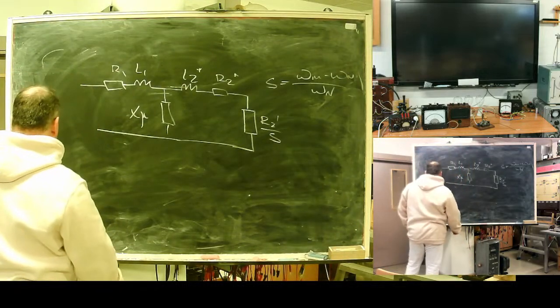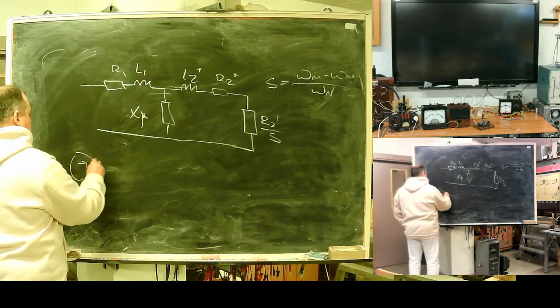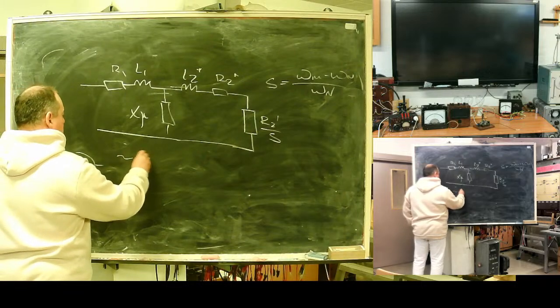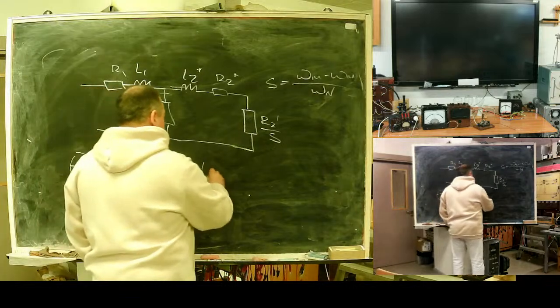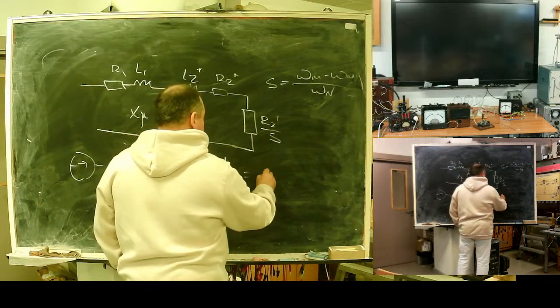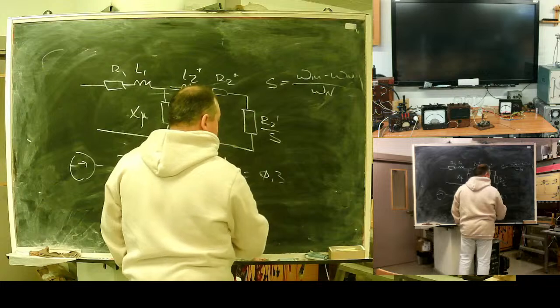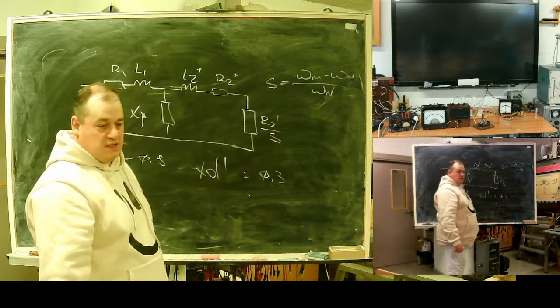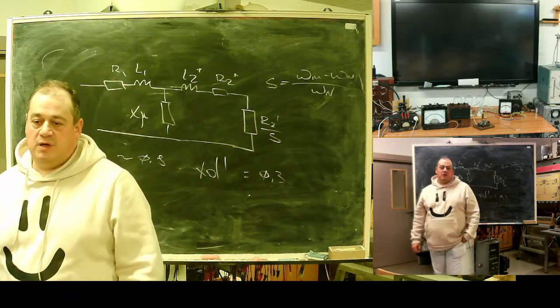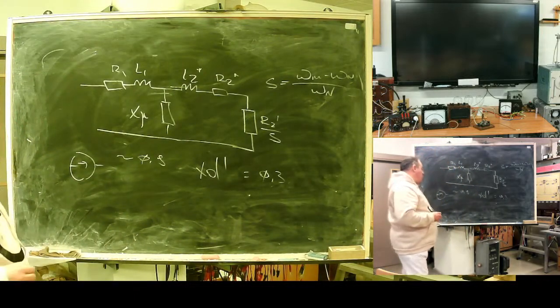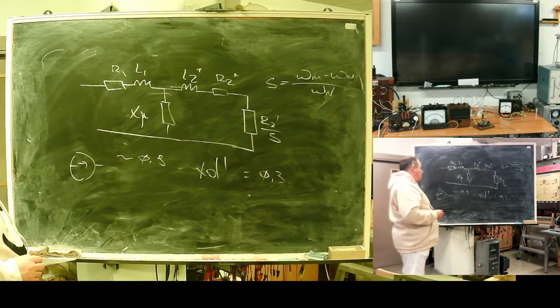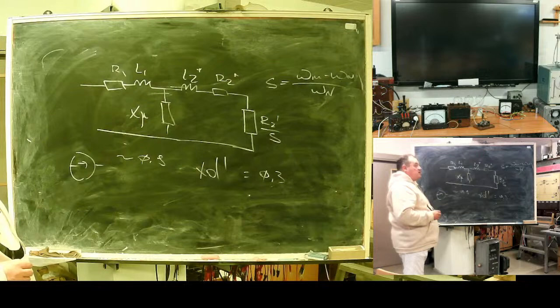For short time you can use EMF approximately 0.9 and transient reactance something about 0.3. For quite stable modes, you can use simple transient reactance. That's for direct sequence.